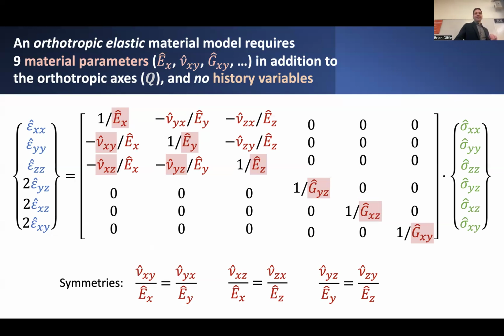All right. So that's orthotropic elasticity, a little bit more complicated, but nonetheless elastic and with no dependence on any kind of history or variables of interest. So we still assume that for orthotropic materials, there's no inelastic behavior. So we can still apply the same concepts, determine the stiffness matrix or the tangent modulus of the material as just the inverse of this matrix shown. You'll notice I've defined this relationship as the inverse: given stress, determine the strain. But you could just as well take this matrix, invert it, and now you have the tangent modulus of the material.